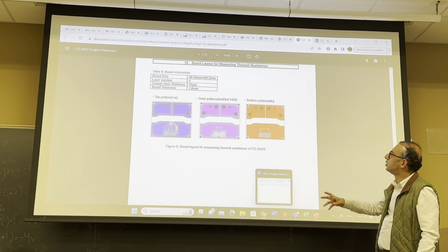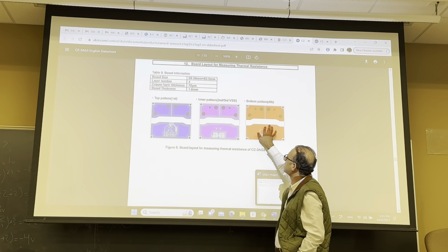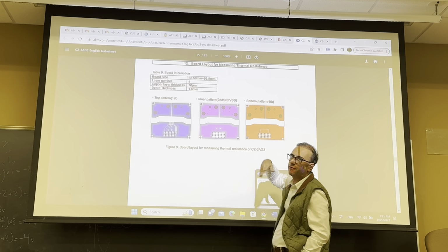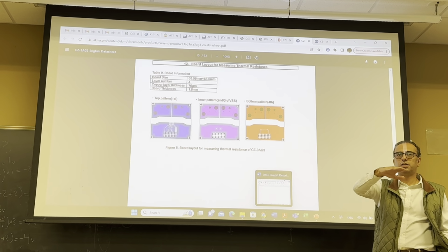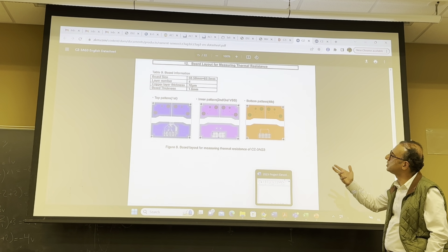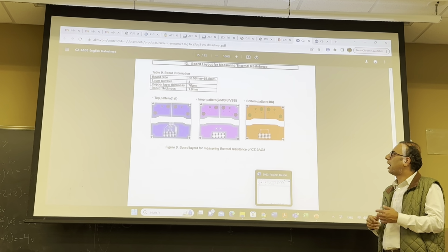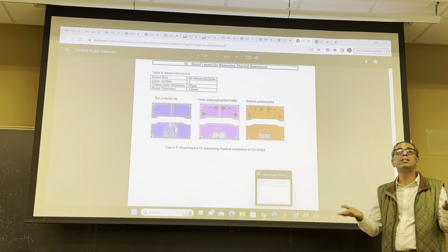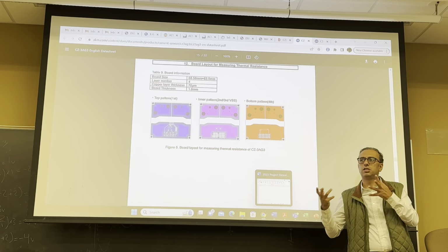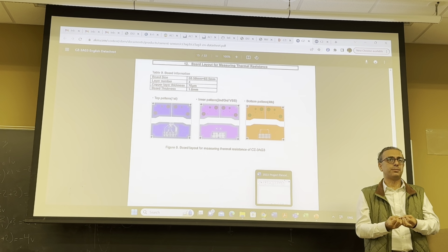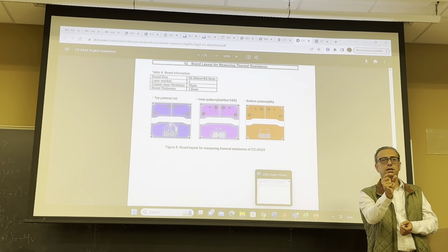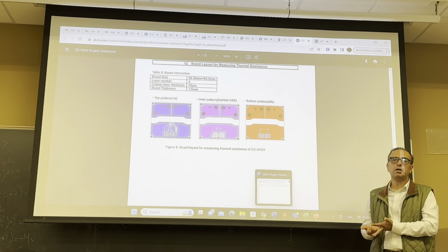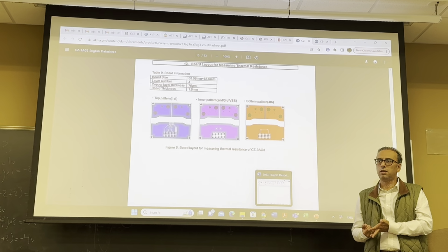Number two, although your sensor is just sitting here, as simple as that, you see the top and bottom layers are filled with copper at different points. These are things they do to basically cool down the sensor, because this sensor carries like 20 amps in this tiny IC. So there are some thermal considerations as well when you choose.